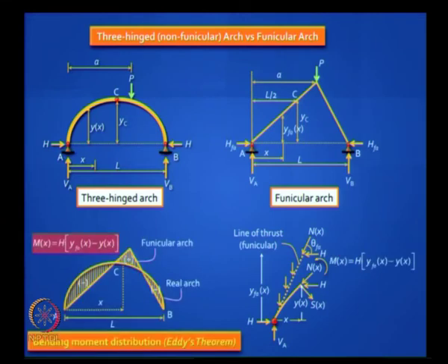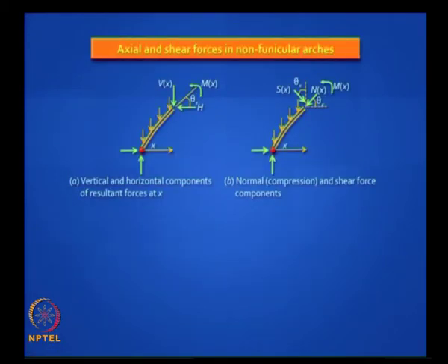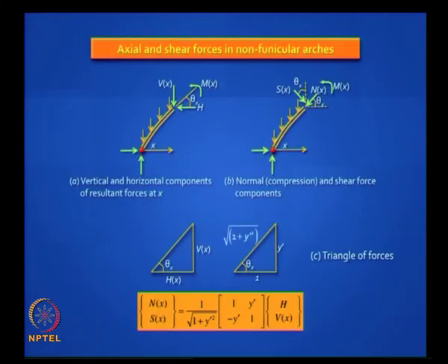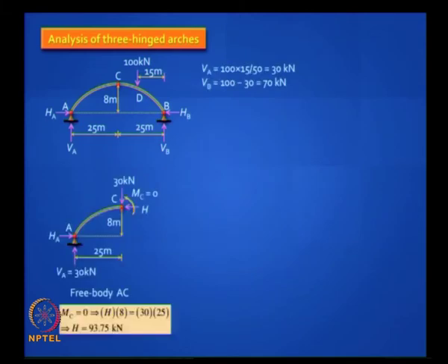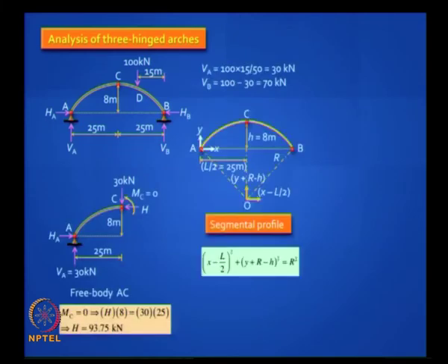The other thing you need to know is you will also get shear forces and axial forces. You can resolve the vertical force and the horizontal thrust into axial and shear forces using the geometry of the arch. You have studied all this, and these are simple examples that can be solved.